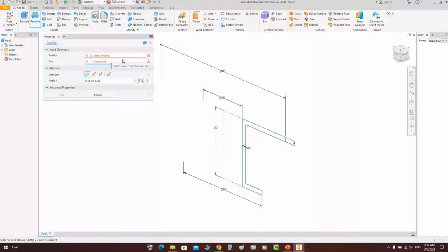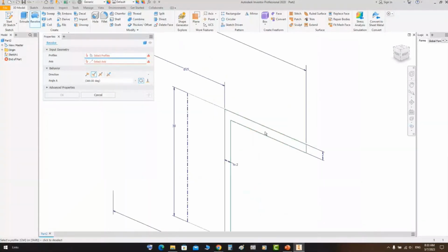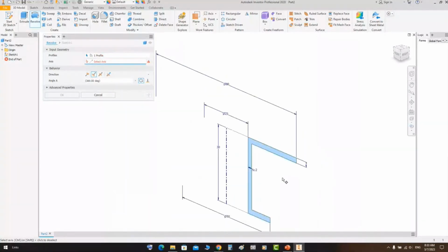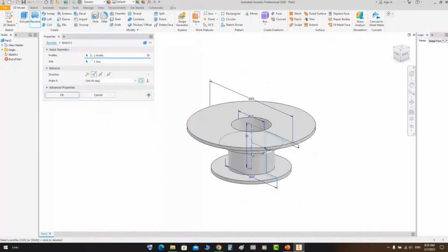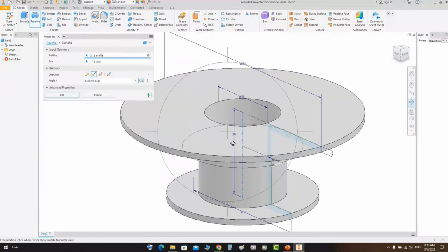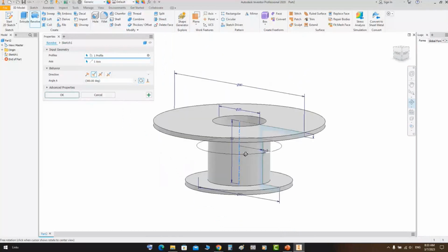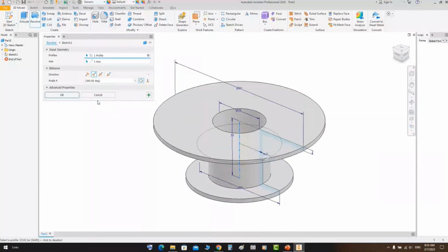As we discussed, you can make it as a surface or as a solid. We discussed that we will need the surfaces in the next steps, inshallah. But right now we need to learn how to make solids. So from here, let's select the profile. You can select the closed area from here. After that, you can select the axis of rotation. So you will get the feature like that as a revolve.